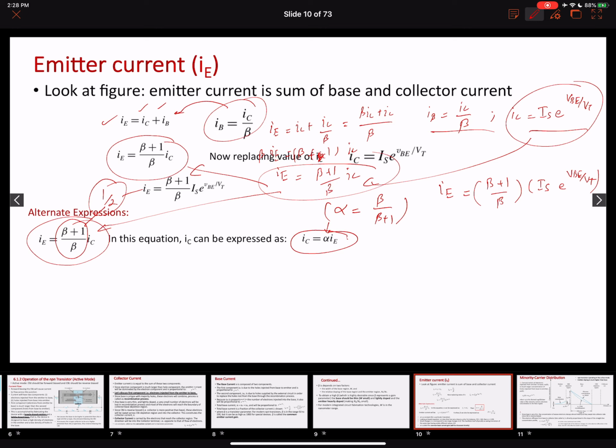But just by looking at this equation again, I can see that over here alpha equals IC over IE, right? So if I compare that to the beta, alpha also looks something similar. It's a ratio of the current values, so it's also a current gain factor, a ratio of the collector current to the emitter current with a base common.